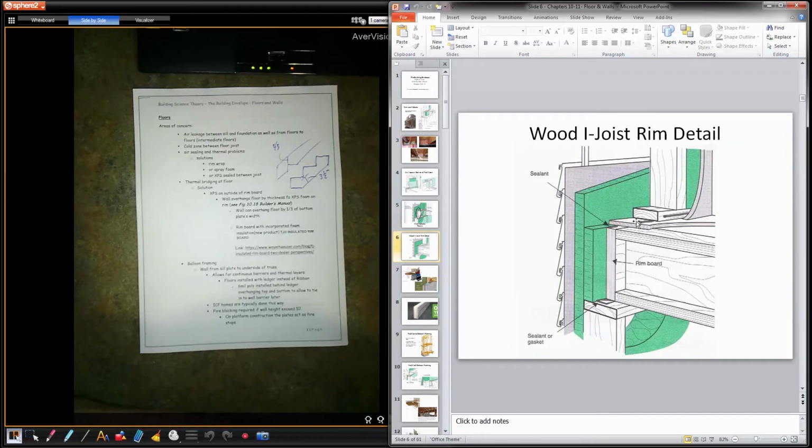Again, here you can see lots of acoustic caulking. It comes in a tube. A little messy, but it does a good job. You can see they have it everywhere between layers, right? Is it necessary? So if I have a good air barrier, sealed 100% on the outside, are these beads necessary? No. But a good idea. Okay.